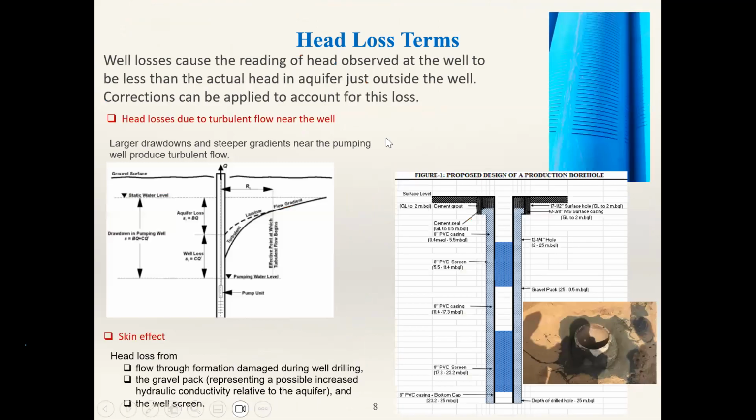Right. Now we are going to use this radial flow equation for the pumping test. Because before that, I will discuss briefly about this pumping test. In the pumping test, what we normally do is we drill a well that we use for pumping water out. In addition to that, we drill a couple of observation wells. This can be the first observation well. Somewhere here, there can be another observation well.